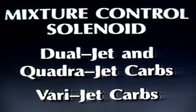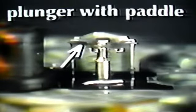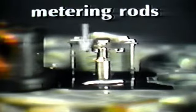Essentially, the mixture control solenoid works just like a starter solenoid. It operates through being energized by an electrical signal. When system voltage is added to the solenoid, it is routed through the ECM, which then decides at what point to energize the solenoid based on carburetor needs. More specifically, the MC solenoid affects the operation of certain carburetor parts, including the spring, the plunger, which has a paddle attached to it, and 2 metering rods underneath the paddle.